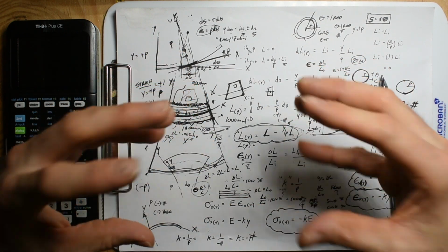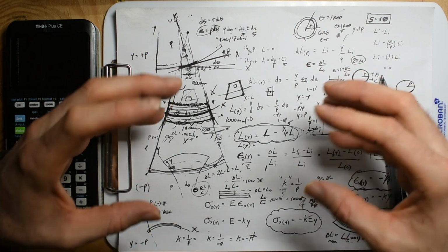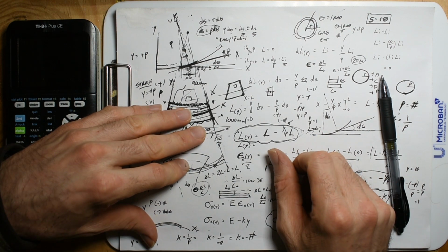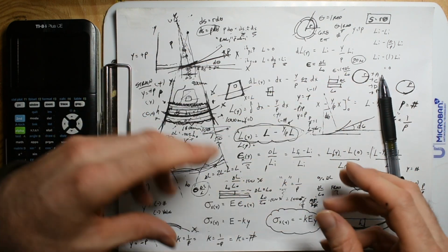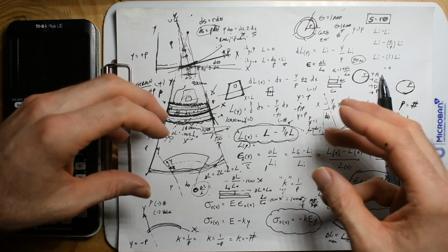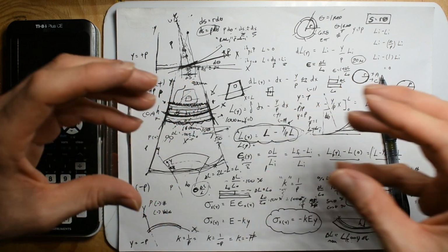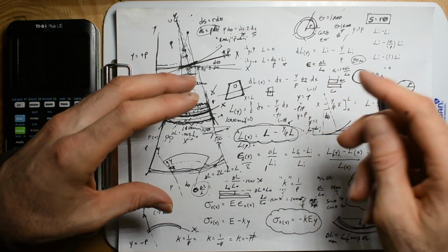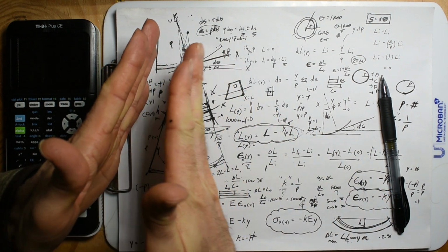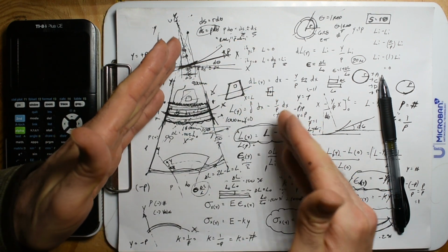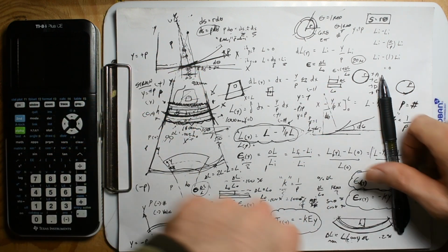If the max strength is 58,000, that means there's 58,000 pounds of pressure on the surface area, and if I know the surface area, that directly links to pounds. So with a 1 inch rod of steel, 58,000 pounds stretches it 2 millimeters, 1 millimeter is 29,000 pounds, and anywhere in between, a fraction of a millimeter will line up linearly with a certain amount of pounds that I put on it.